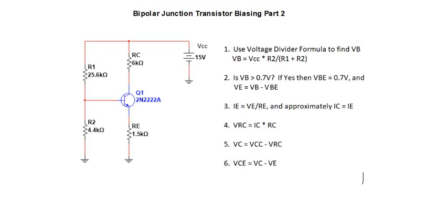And then by choosing our base voltage through this voltage divider, we're going to narrow that down to a single point we call the Q point or quiescent point. And as we stated before, we want that to be roughly halfway in the middle of that load line, so I have room on both sides. If I put an AC signal in, there's room for the amplified AC signal to move back and forth without getting chopped off by one of those endpoints.